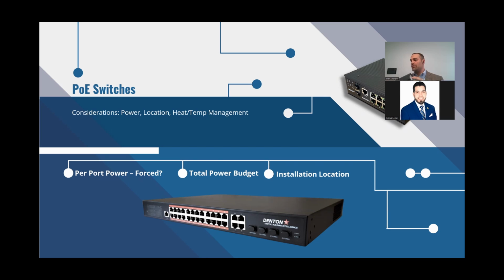So I'm going to encourage you, our switches are specifically designed for PoE lighting. They're designed so that you don't change any of the settings. You plug it in and it's going to work full load. But if you're not familiar with the manufacturer and you're trying out a new switch, give it a test. So that's the per port power and the note on that forced or not forced. There's also a question of the total power budget or power groups. Different manufacturers group their power or have a different power budget for the switch.